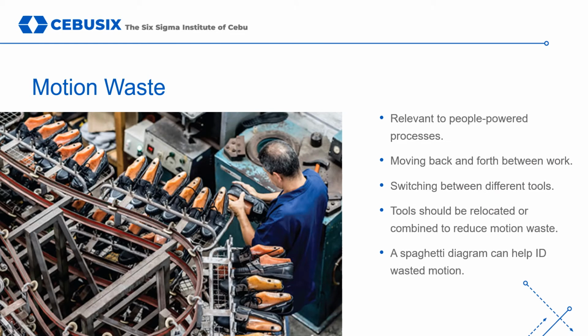Motion waste is any excess movement, whether by employees or machines, that does not add value to the product, service, or process. This is different from the waste of transportation, which is a result of having to unnecessarily move people, products, or equipment. Poor process design and controls and poor workstation layout are some of the most common causes of motion waste within an organization. But shared tools or even isolated workers can result in motion waste as well. The solution is to rearrange layouts to decrease the distance between stations and make it easier to reach things that are often used.